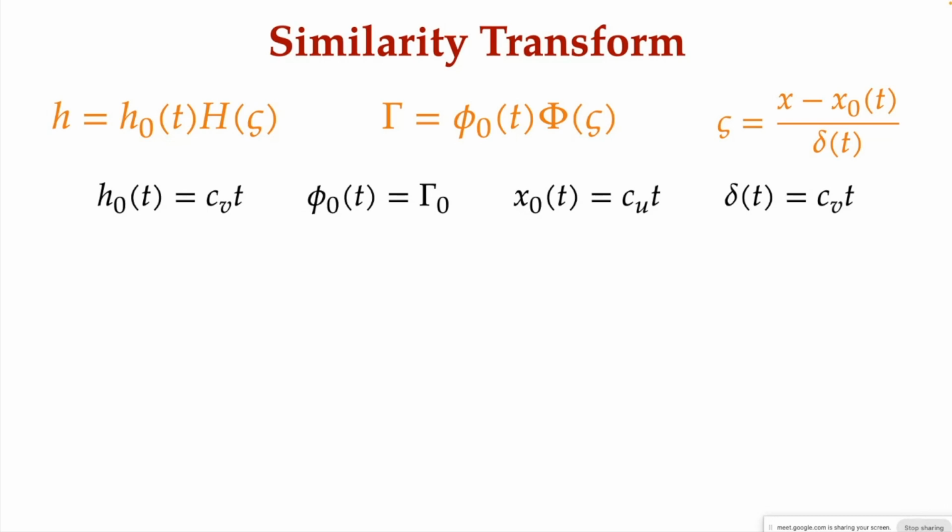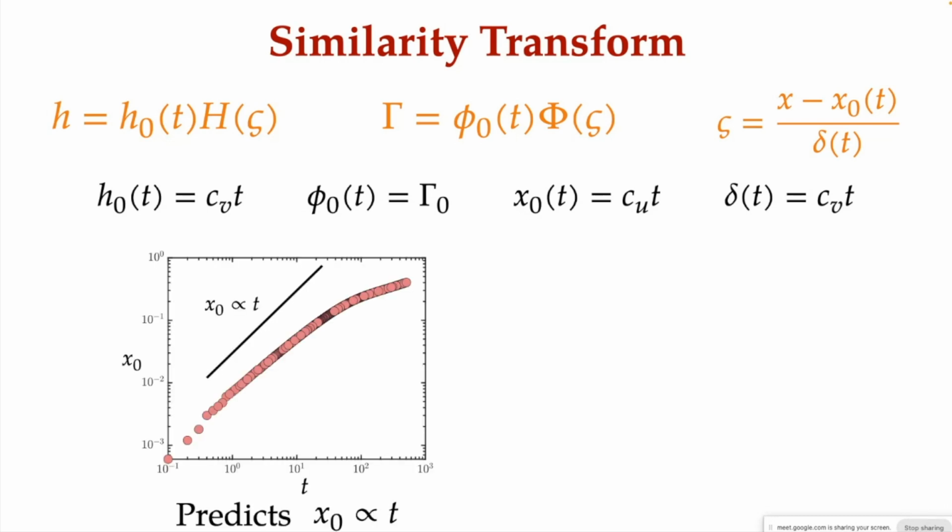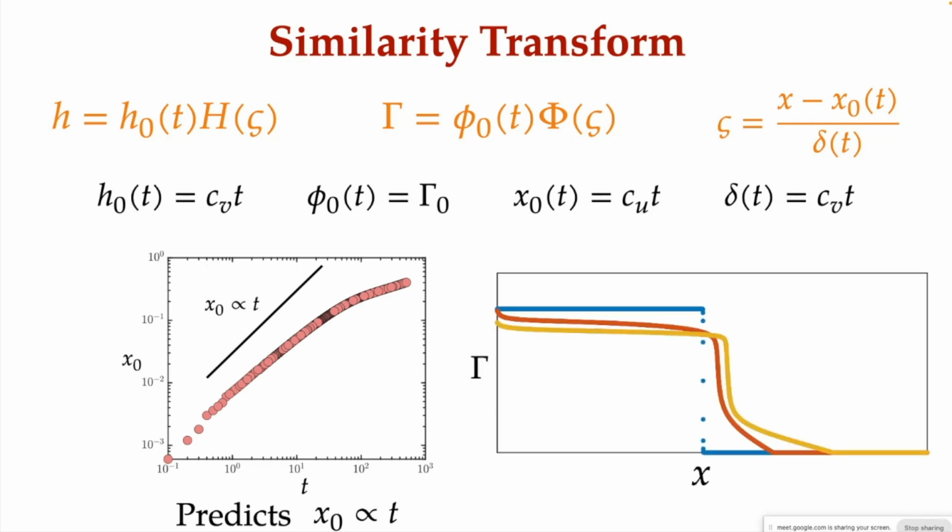There are two good things about it. First of all, x0 is linear, which is what we also see. So x0 is proportional to t. And the other term basically means it's independent of time, which also makes sense, because since there's no diffusivity, your surfactant profile will more or less remain the same height, but it just convects towards the right. But the other delicate term is h0, which is proportional to time. What could be is that this coefficient for time, CV, could be very much smaller than your coefficient for your horizontal movement. And so in our equations, we just don't see this net going upwards.